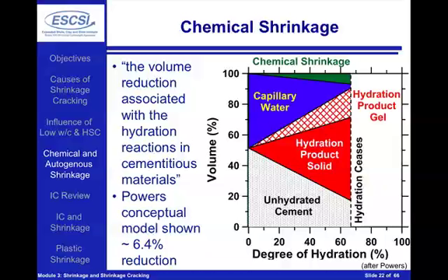When we start to talk about supplementary cementitious materials, the chemical shrinkage goes up. So with a C fly ash or a slag, we may see this number going up as high as doubling. When we see other materials like silica fume, where we have the pozzolanic reaction, we can see this going up even higher, to 3 or 4 times the value of chemical shrinkage of Portland cement.